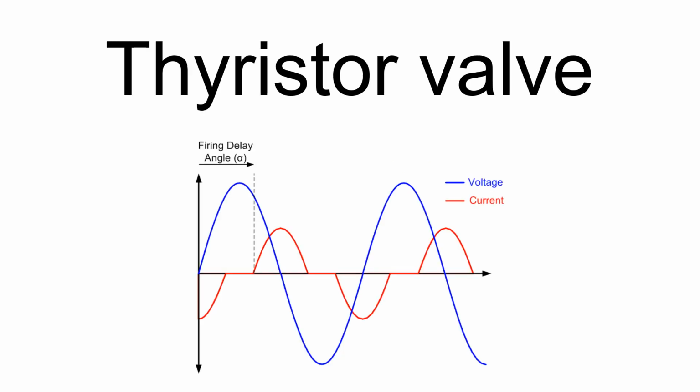The thyristor valve typically consists of 5 to 20 inverse parallel connected pairs of thyristors connected in series. The inverse parallel connection is needed because most commercially available thyristors can conduct current in only one direction. The series connection is needed because the maximum voltage rating of commercially available thyristors, up to approximately 8.5 kV, is insufficient for the voltage at which the TCR is connected. For some low-voltage applications, it may be possible to avoid the series connection of thyristors. In such cases, the thyristor valve is simply an inverse parallel connection of two thyristors.